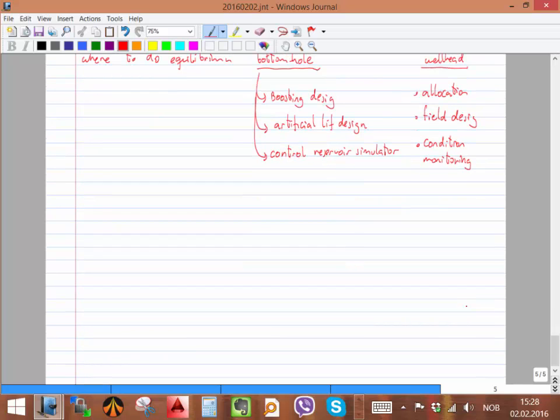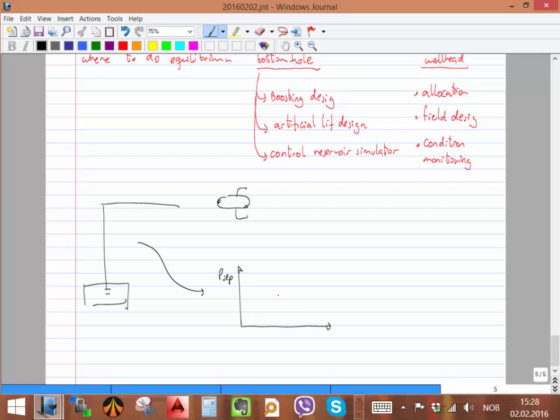So let's maybe, just to be sure that you understood the concept, ask: what happens if we have this system and we select the point just at the separator? Let's now separate the systems. I separate, and I want to calculate the available pressure curve for this system. So what will that be? P separator versus Q is going to look something like that, right?